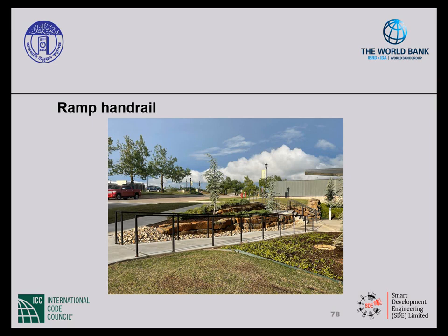So here's another example of a ramp, and why I wanted to show this picture is that while we do have handrails on either side of the ramp, and the handrail extensions are provided and do proceed to the ground, at the base of the handrails we don't have edge protection.